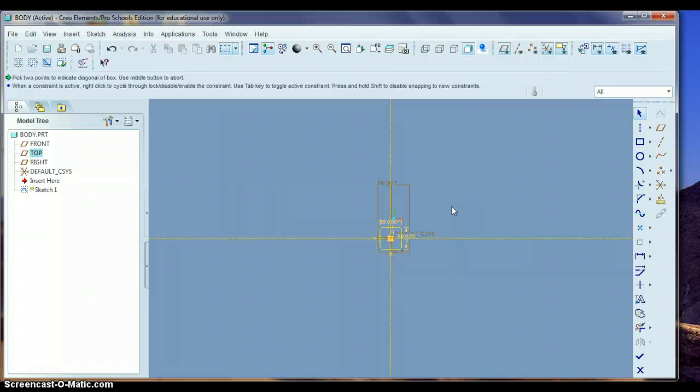Okay, so to make our catapult here, we're going to draw this rectangle, and again we use the center lines. We drew until we saw the little red arrows pop up, and now it's time to resize this. And so this measurement here, we're going to change that to 5 inches, and press enter.